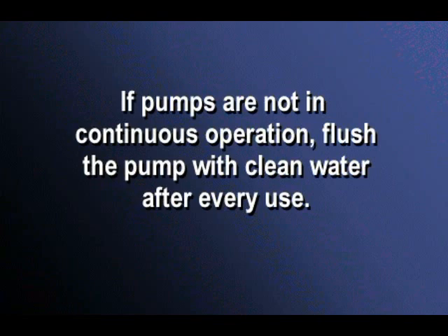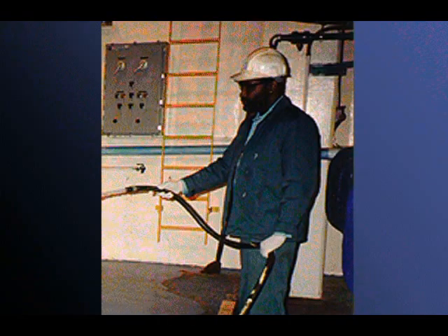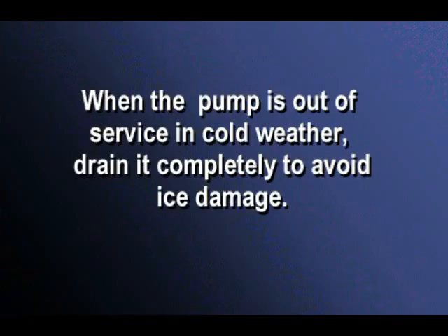This includes sludge, wastewater, mud, and chemicals. Normally, pumping clean water through the pump for several minutes will be sufficient to clean it. Before storing the pump for a long period of time, be sure to thoroughly wash all accessible parts. Before storing the pump during freezing weather, drain all liquid from the pump body to prevent ice from cracking the pump. Remove the ball valves to let the pump drain thoroughly.